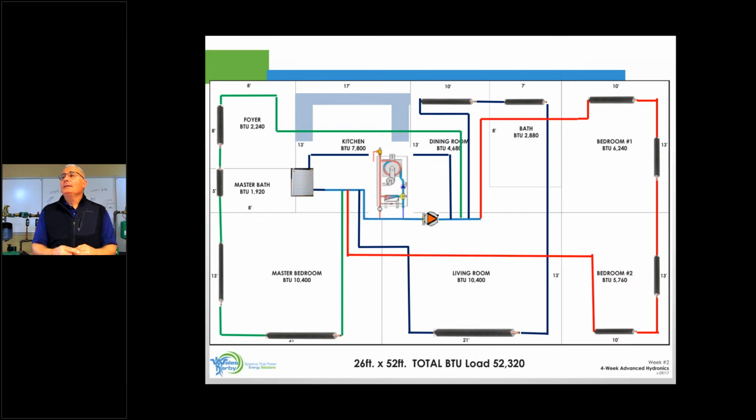Yeah, I'm a fan of radiant. I really like radiant. When I first got here at Wales Darby, we didn't have a radiant line, and we sold a pile of Beacon Morris kick space heaters, and we still move them a lot. But there's a tendency sometimes they could be noisy. I'm blowing air across the floor. Anytime we're moving air and heating, there's a chance that people may be uncomfortable. Radiant could be a nice option. Even a radiant ceiling could be a nice option if I don't have enough floor space because there's an island in the middle taking up available floor. We can do radiant in walls and ceilings also.